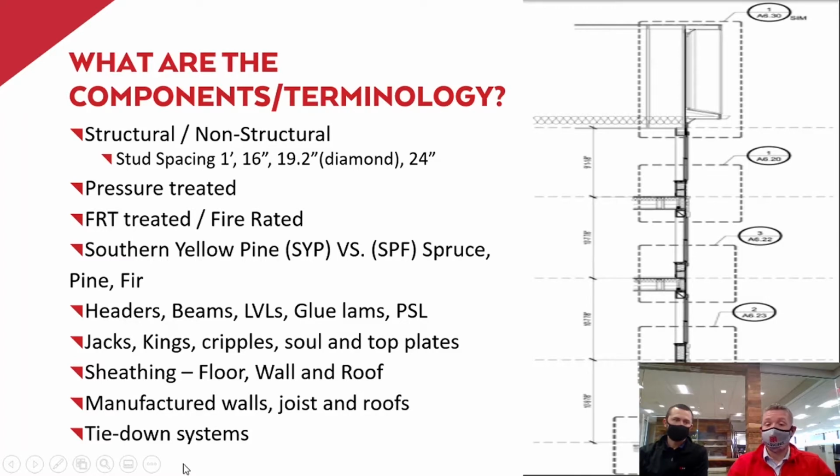One thing I didn't mention in the slide is shear walls. Shear walls are another item that we're seeing more and more of today in wood framing. They do not vary from a normal wall very much. The stud spacing may be slightly different, and the plywood makeup may be slightly different, but the nail pattern is most definitely different.